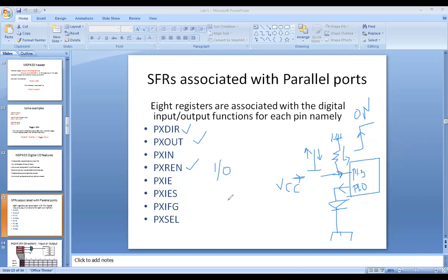Now, hope everything is clear. I can talk about another combination. If you drive one end of your switch plate with ground, the intelligence is you have to pull it up. Am I right? Now you have to pull this resistor to VCC. So when the switch is off, you will read VCC. When the switch is on, this VCC is shorted to ground. That's it, because of this resistor. Am I right?